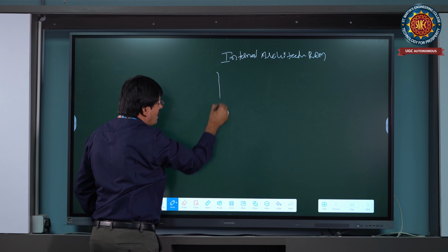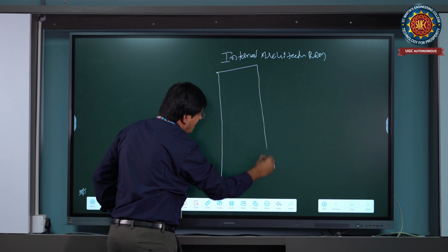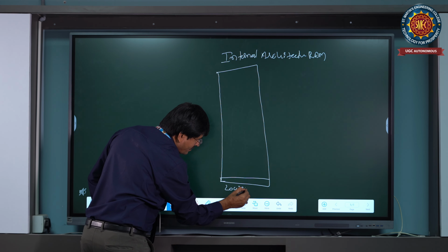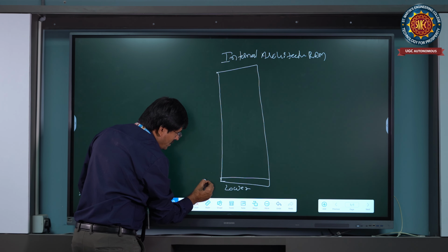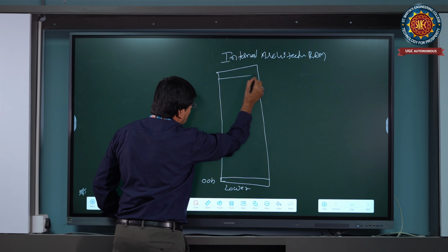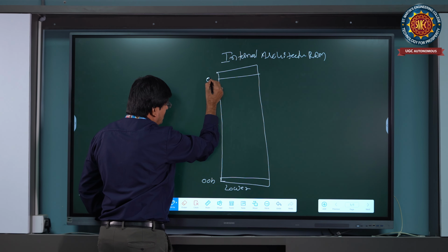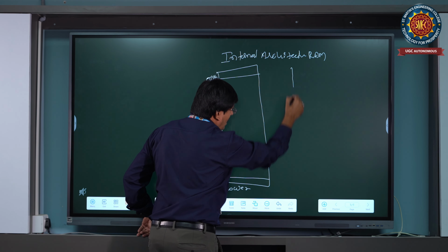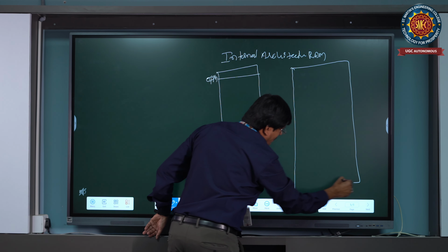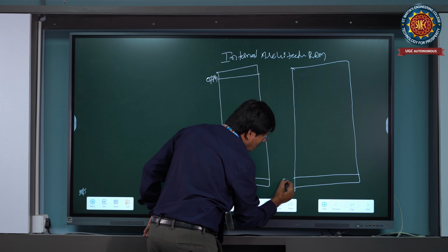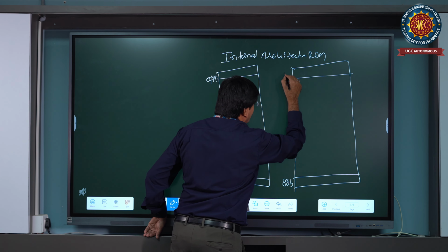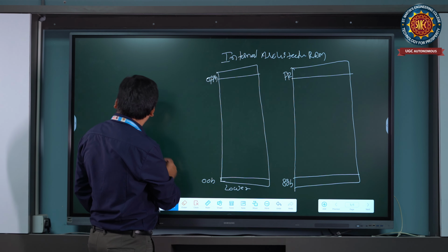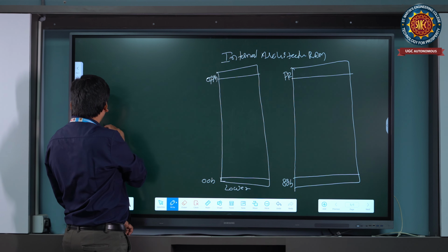So we can see the upper RAM and the lower RAM and their occupied addresses. The lower RAM always starts from 00H to 7FH, and the upper RAM is addressed starting from 80H to FFH. We will see that organization in the slides.